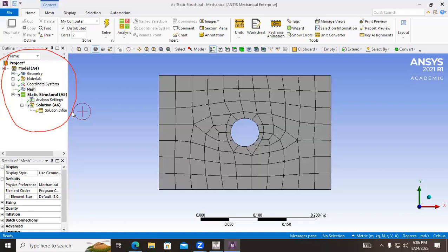You can see that Ansys basically took our geometry and broke it up into a bunch of, in this case, squares, or at least four-sided polygons. Each has four sides, four edges, and even all of the elements near the hole, they may look distorted, but if you actually look at those elements, they should have four sides. Some of you may have triangles, since sometimes Ansys defaults to triangles, but either four-sided or three-sided polygons, you should have a mesh that looks something like this.